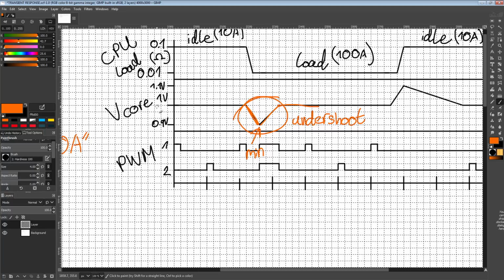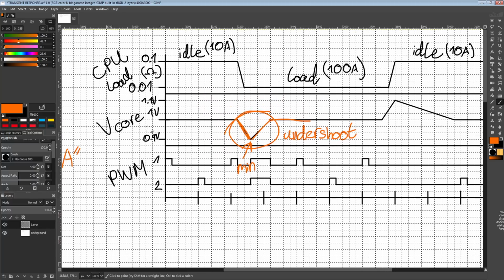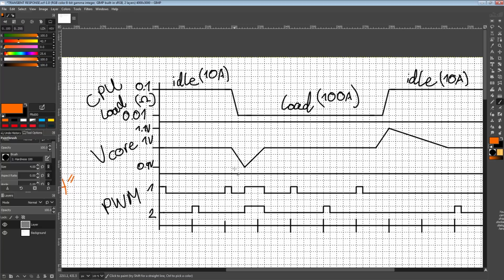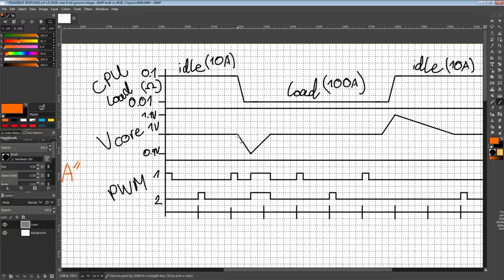So with this 1 volt target voltage, we here have 100 millivolts of undershoot because that's a 100 millivolt gap. So that's 100 millivolts of undershoot. Another easy way to think about it is, if you're measuring a voltage regulator that's running and you hit it with a transient load, the lower the minimum voltage it hits during a transient, the worse the transient response is, right? Good transient response is having a very small deviation in the voltage.